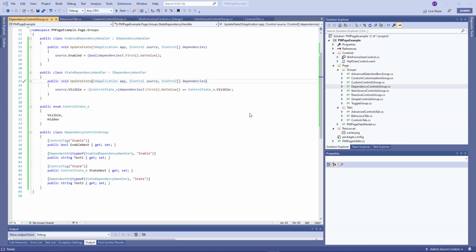All the examples previously demonstrated in these tutorials require you to have a class at compile time, which means you cannot dynamically create controls at runtime. Although in the majority of cases you will not need to create your controls at runtime, there could be situations where it could be quite handy. In this section of the video I'm going to demonstrate how you can create controls dynamically at runtime using xCAD.net.